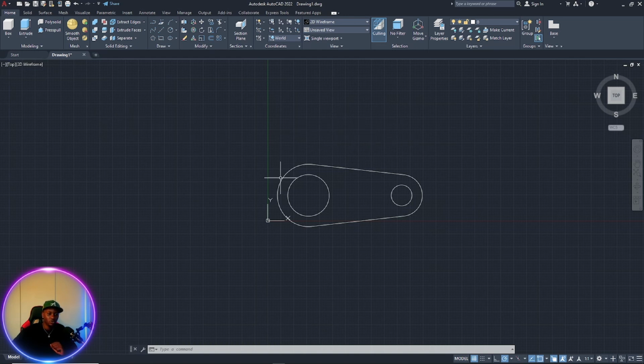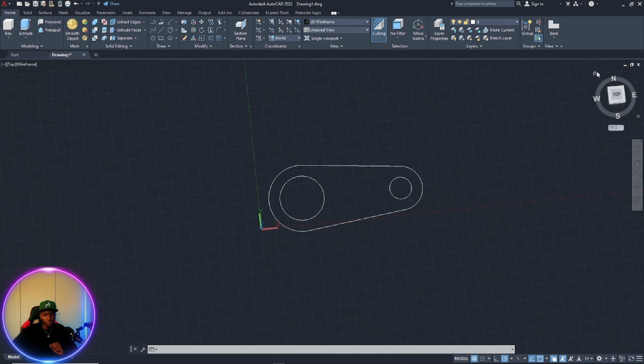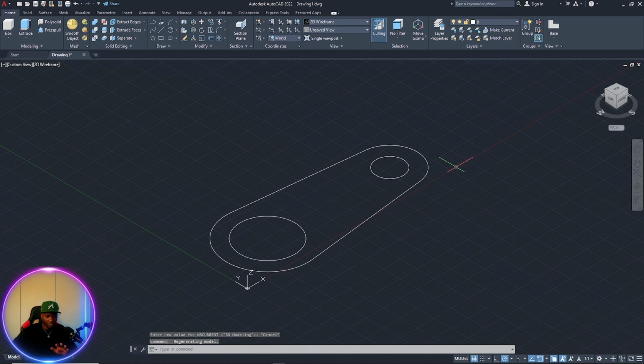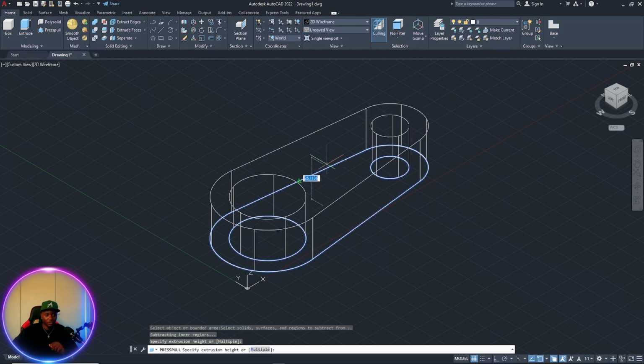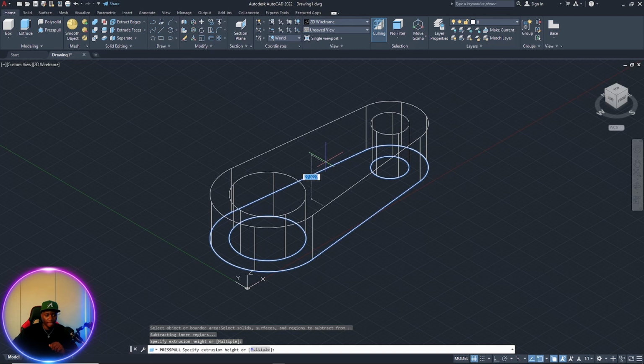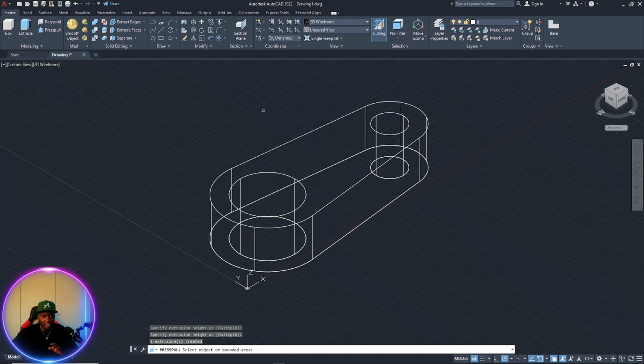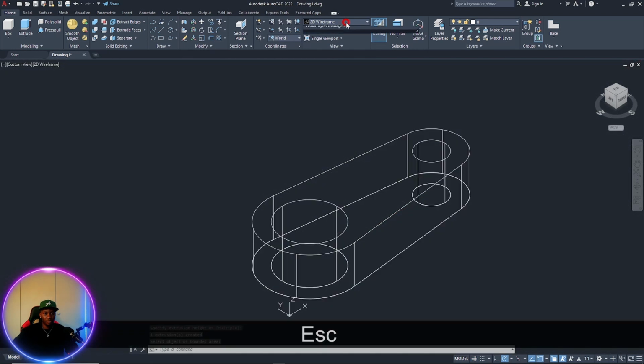So now this is already 2D, as you guys can see. I'm gonna come here, and now it's 2D. So we go to what? To press pull. Come in between this. It's gonna take time, guys. Give it time. Select. We drag it up, right? But as you see now it's in wireframe. You can actually see it, right? We press wireframe.